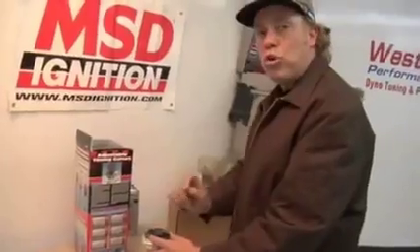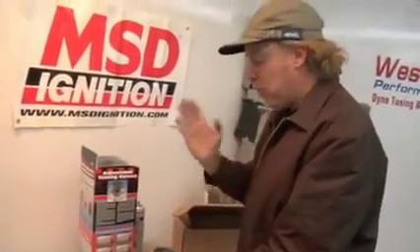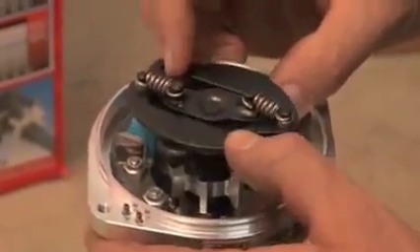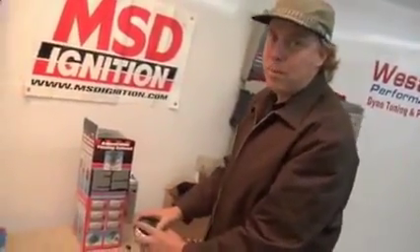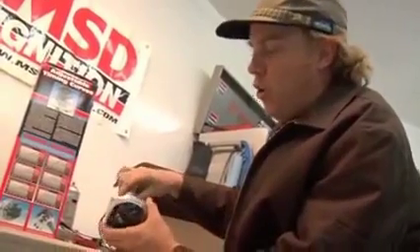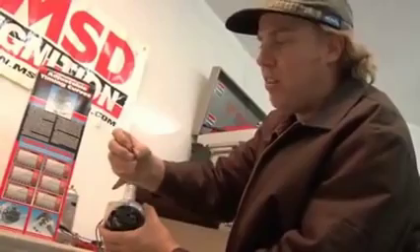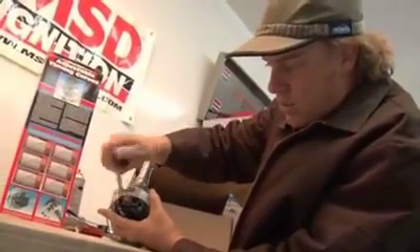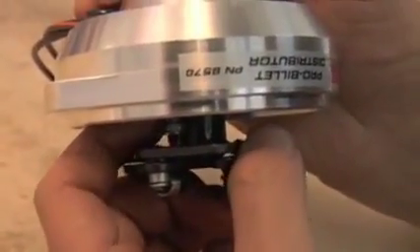You can change the total range of timing within the distributor and the rate at which it goes from initial to total. The lighter the springs that you put on these advance weights, the faster the curve. The heavier the springs, the slower the curve. In addition to changing the rate of the curve with the springs, you can change the overall sweep of timing inside the distributor with these little bushings. And you have to get an 11/32 wrench in here, right underneath that advance weight, and take off a little nut to get to that bushing.